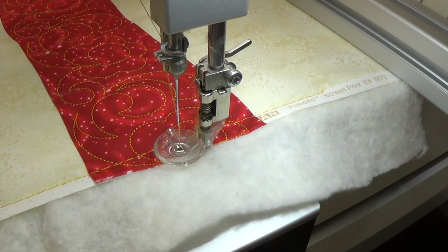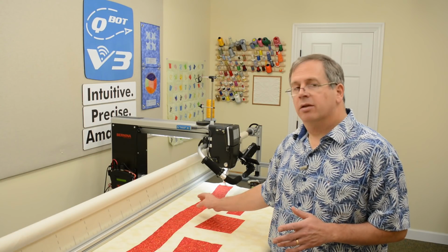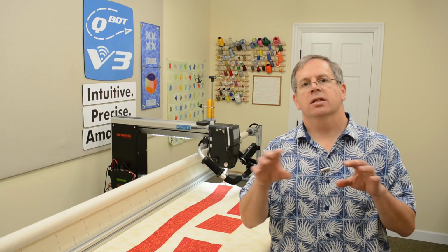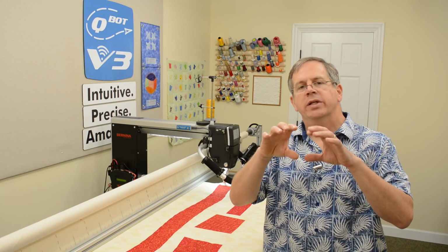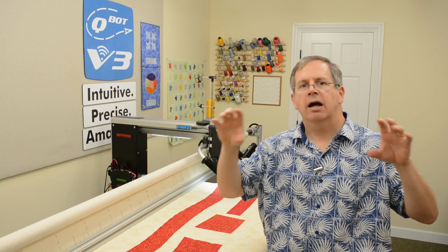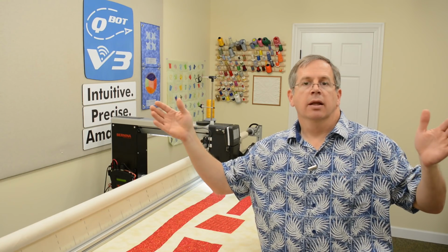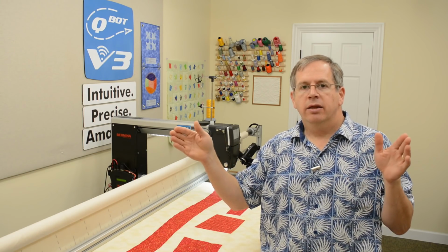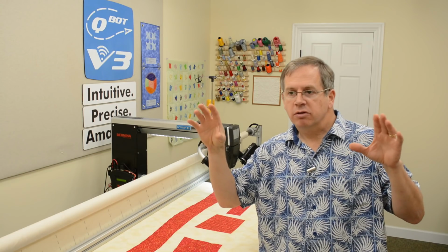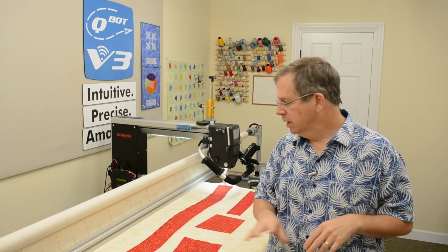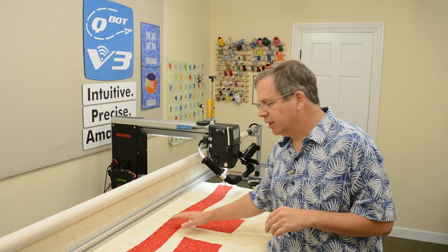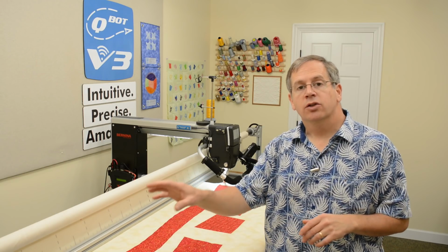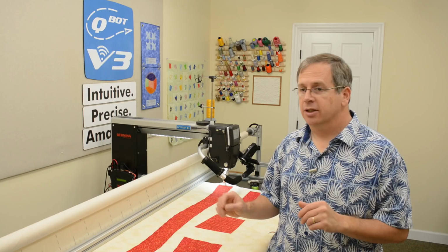So there you have it. Very easily, what we've done is we've selected the points of the boundary, not worried a bit, placed our design, get a basic understanding of how the design should be sized. You know, you have to kind of, with your eye, look at how tall it should be, and you make its length using the chain feature. And then if it looks pretty good, like it should fit, press the Smart Fit, and then boom, it is placed perfectly with a margin. Looks like 0.15 inches to me, like what we had input, thank goodness, right?